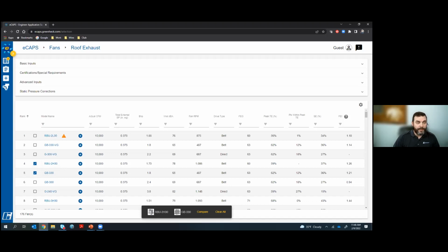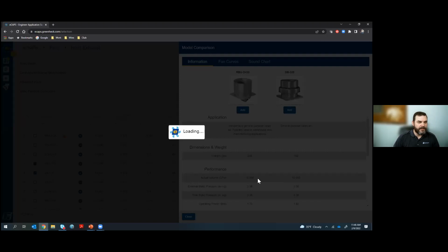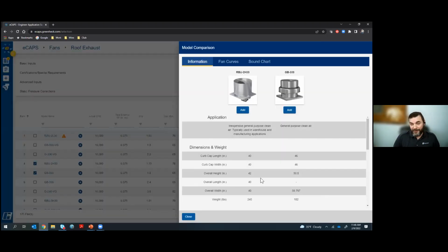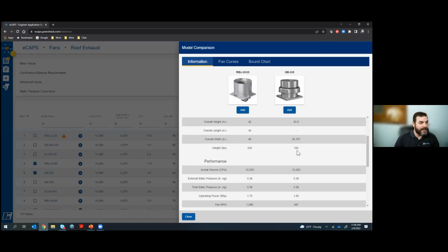And the downblast power ventilator is a 1.21. So both selections, good FEI. Let's just compare and look at the cost here real quick and see if that holds true. And it may, in many applications, be that the more expensive fan has got the higher FEI. That may happen. In this scenario, the more expensive fan has the higher FEI.